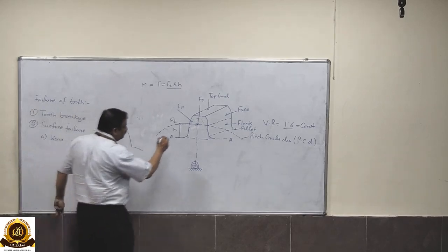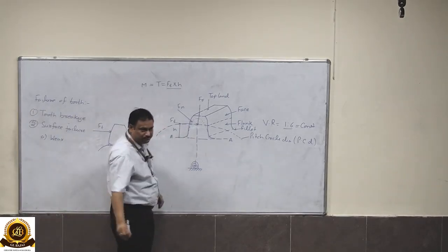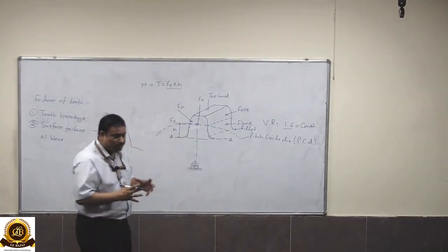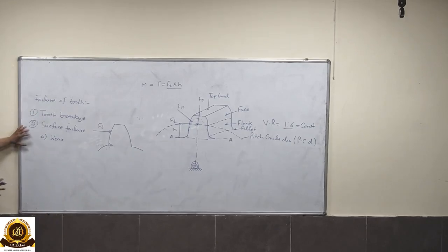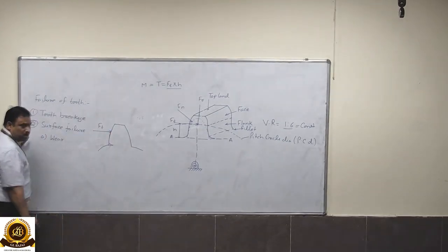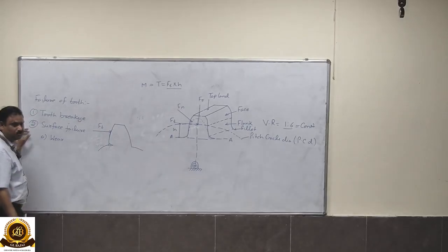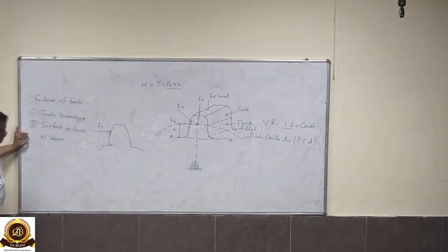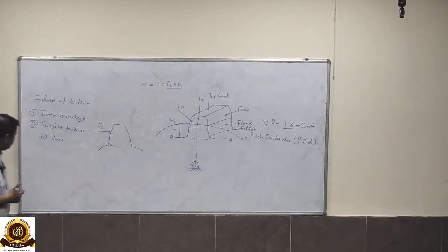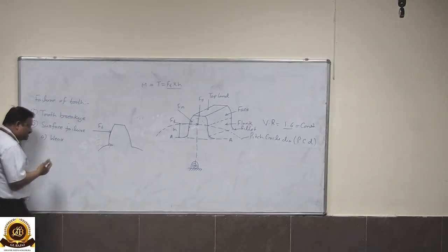So what is happening on the surface? There is friction between the two surfaces, or a compressive effect between the two teeth. Under this compression, or sometimes lubrication failure, the surface is subjected to a very high compressive stress or load, and similarly the material is removed from the surface of the tooth. Under this removal of material, the profile will break. This action is called non-conjugate action.